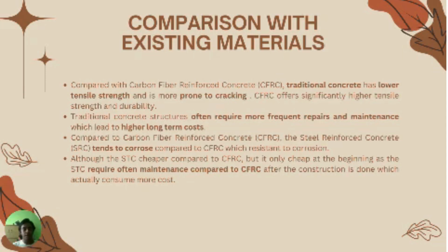Next, it often requires more frequent repairs and maintenance, and higher long-term costs. These are the traditional concretes that use steel as the reinforcement agent. Next, it tends to corrode, as I mentioned, and requires more frequent maintenance compared to CFRC, our carbon fiber reinforced concrete.